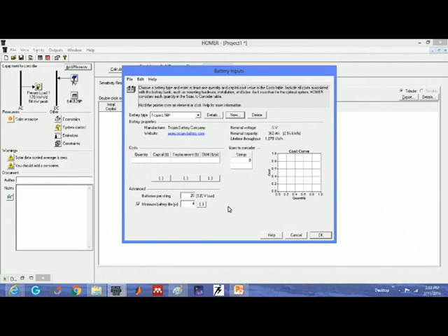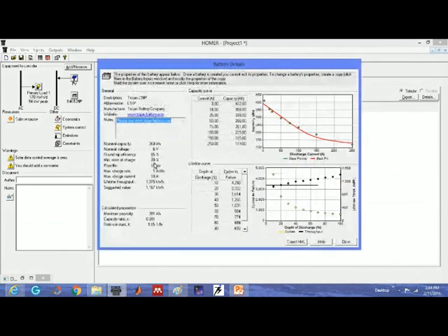Let's say I say that battery should never go beyond 30% of its final value. Let's say one example. That means 30% charge has to be there every time. Suppose you take out total power from the battery and again start from zero. So the life of the battery will change in that case. So we have to maintain that limit. And here I have mentioned the limit. See, details: minimum state of charge 30%.